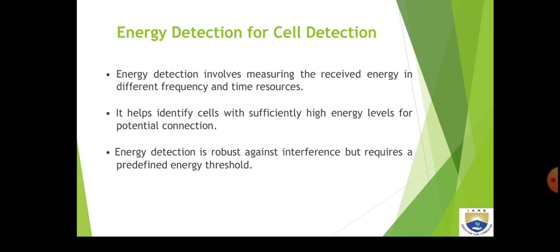Energy detection for cell detection. Energy detection involves measuring the received energy in frequency and time resources. It helps identify cells with sufficiently high energy levels for potential connection. Energy detection is robust against interference but requires a predefined energy threshold.